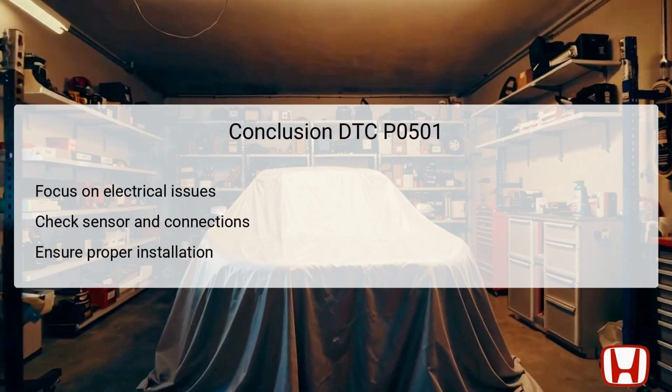In conclusion, attention to DTC P0501 should concentrate primarily on electrical issues rather than mechanical faults within the transmission. The diagnosis process particularly emphasizes the importance of checking the integrity of the CVT speed sensor and its connections to the TCM.